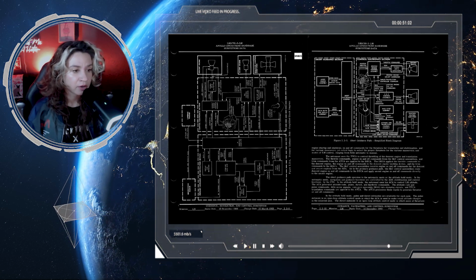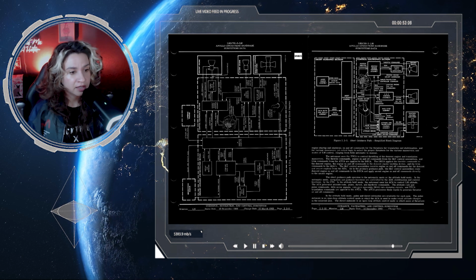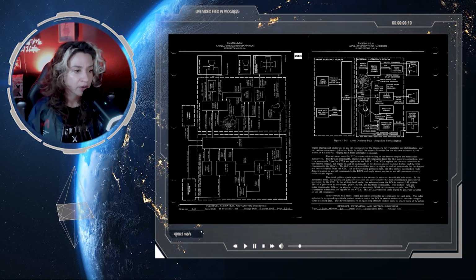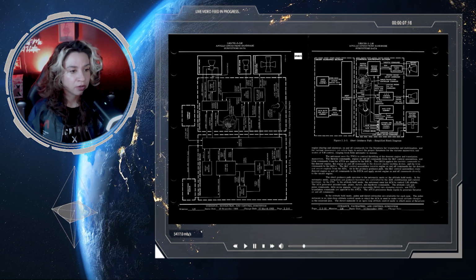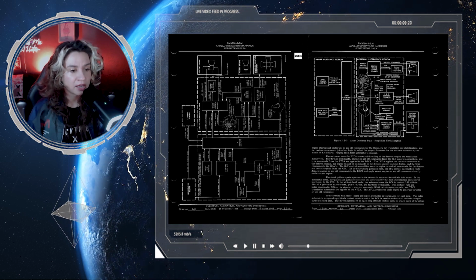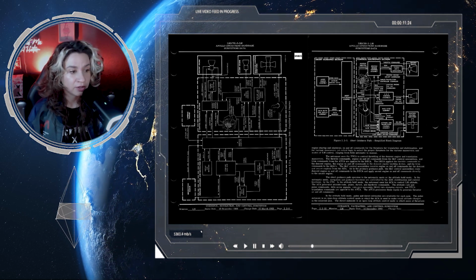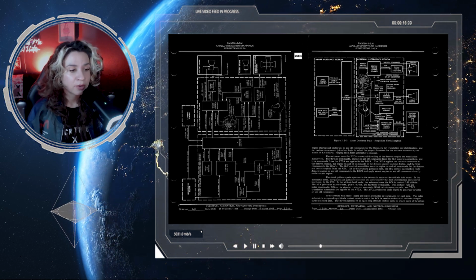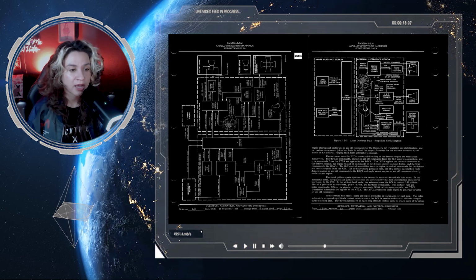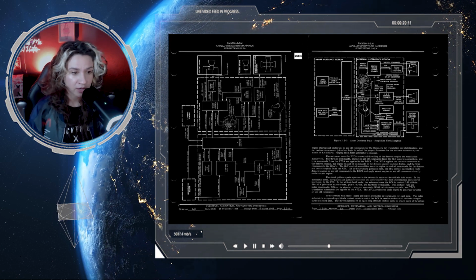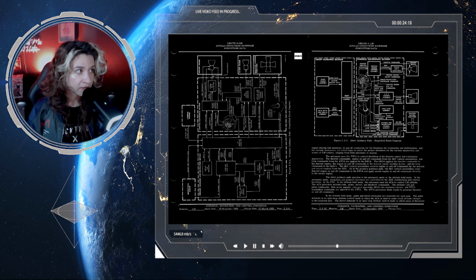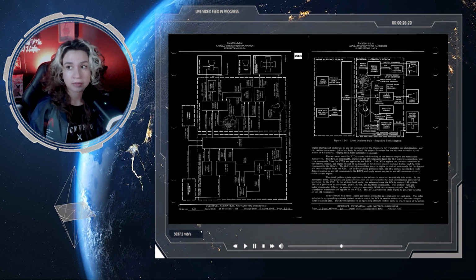In the attitude hold mode, pulse and direct submodes are available for each axis. The pulse submode is an open-loop attitude control mode in which the ACA is used to make small attitude changes in the selected axis. The direct submode is an open-loop attitude control mode in which pairs of thrusters are directly controlled by the ACA.